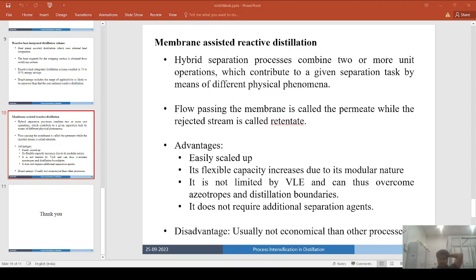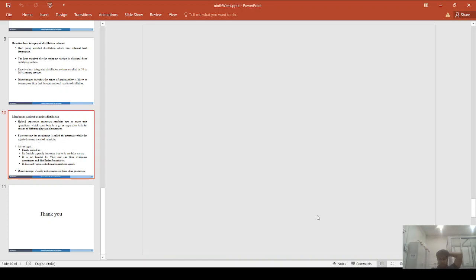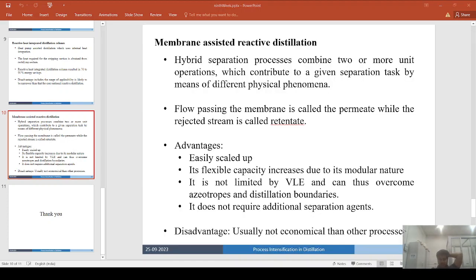Now, what are the shortcomings of high G? The shortcomings of high G include that operation at high gravity may result in erosion of the catalyst, which is entrapped in the internals, for example, like a wire mesh, where very low liquid holdup and correspondingly low residence times may limit the application to reactive systems with very high reaction rates.